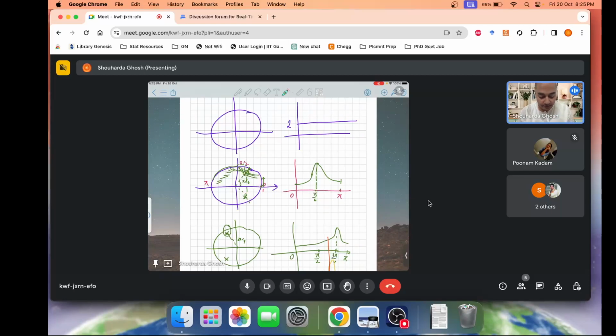So as you're moving closer to the pole, you are actually climbing up indirectly. As you move closer and closer and you move exactly perpendicular to the pole, you have the peak. And once you move past this pole, it starts dipping. So whenever you have a pole, as you move towards the frequency of the pole, you will get to see peaks and dips.